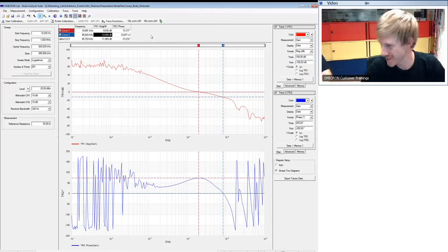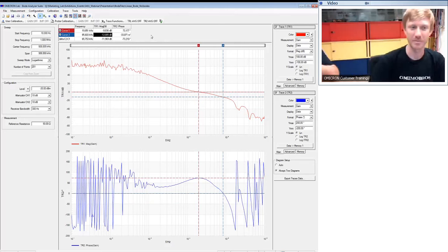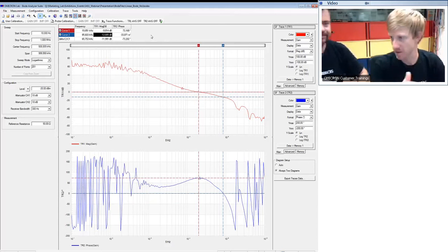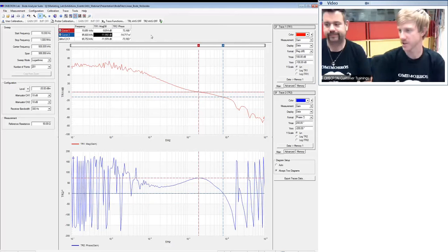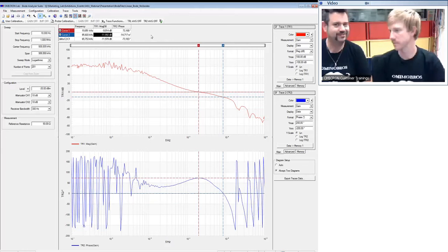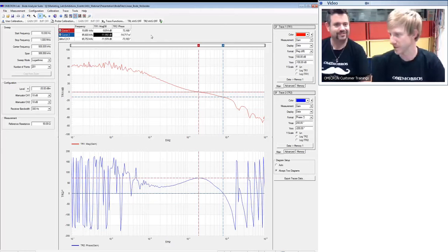In my opinion, yes. And the rules of thumb say more than 45 degrees of phase margin and more than 10 dB of gain margin. Well, it depends a little bit on whom you ask. Some people are happy with 20 degrees. Some people would like to have more than 60 degrees.